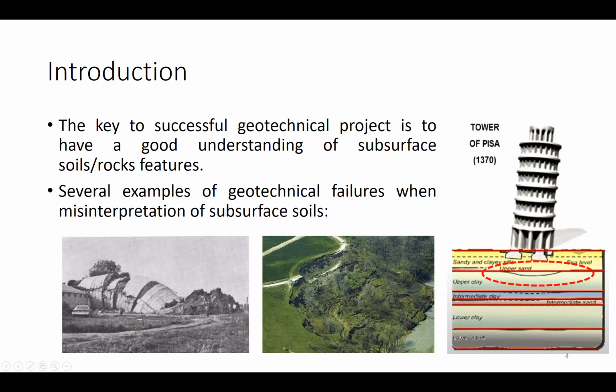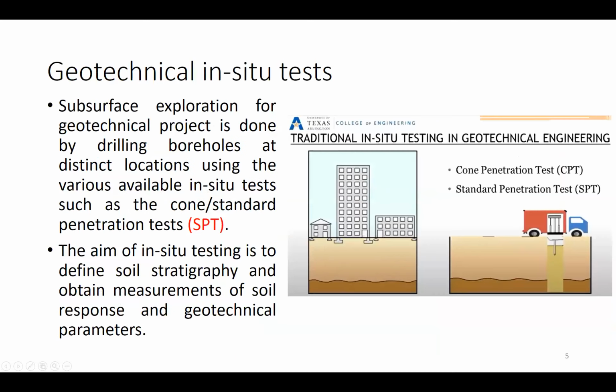One big mistake is thinking the layers of soil go in a straight line, but in reality, they have many variations, not only side to side, but also up and down. To avoid this mistake and make geotechnical projects succeed, we need to do something differently. Not just linear interpolation. We need smarter estimation methods such as Kriging, based on geostatistics, and we are going to discuss that a bit more.